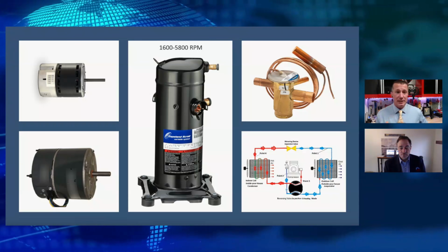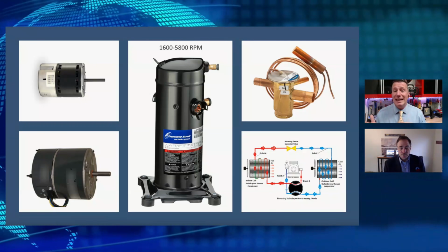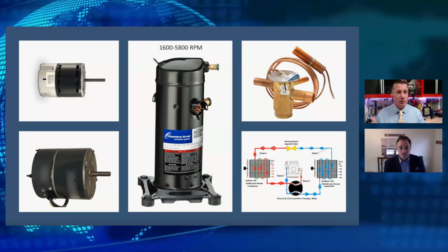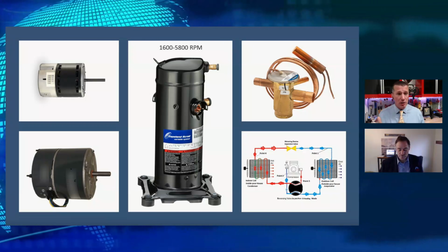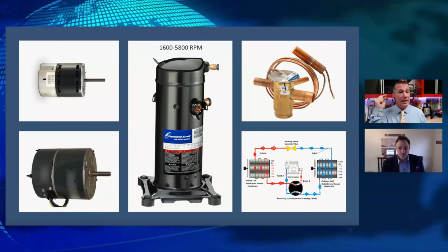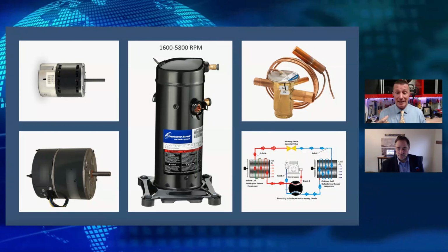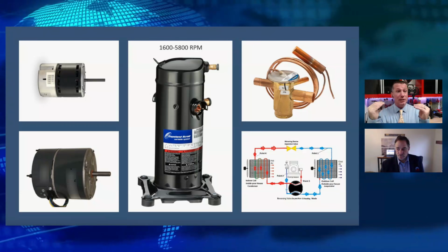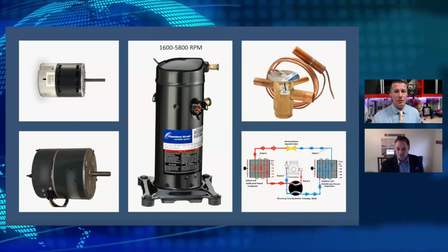Got a lot of efficiency. And even if this was like a 2-stage unit, we could get all the way up to 18 SEER with these in a 2-stage. Now the 2-stage was still just a single speed motor. We didn't change the speed of that 2-stage. Most of the time we just took a hot gas solenoid and we bypassed some of the discharge gas right back into the suction. We reduced the capacity on that. So single speed on those PSC drives.